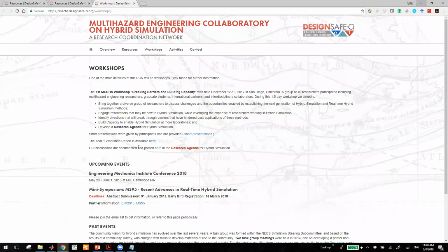But internally, I think the challenge, especially in hybrid and real-time hybrid simulation, is still the boundary condition loading. If we can really reproduce the boundary condition, including the shear force, moment, and displacement, all coupled together, if we can control with high degrees of freedom of actuators and provide exactly the same load to the physical component, I think the result will be of higher quality.